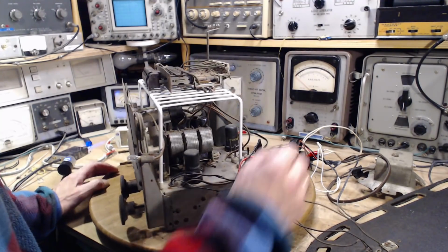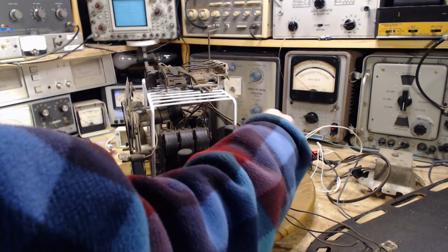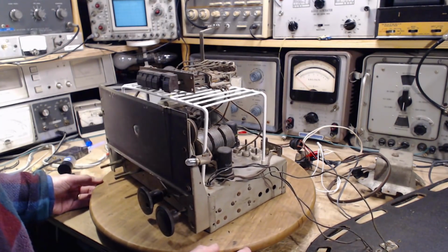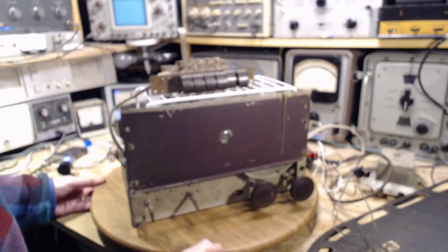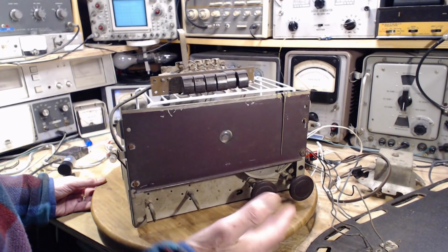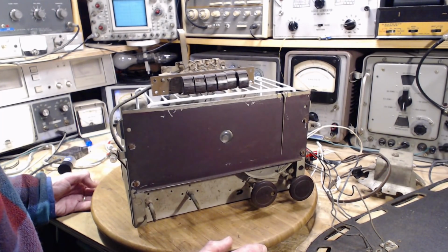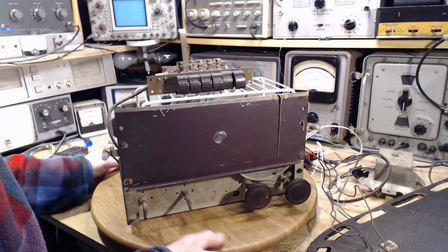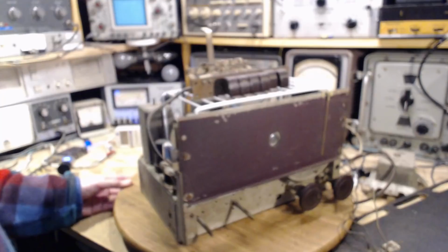So that's kind of interesting. Why is it distorted? Maybe we can start working on this radio from that point of view. Distorted audio output. So there's a number of possibilities, of course. The radio is still full of bad capacitors, so a bad capacitor could be causing this problem. But there's other possibilities too here.